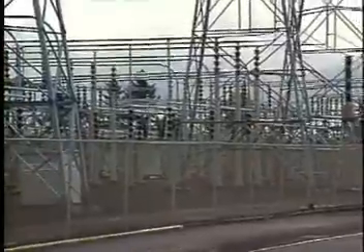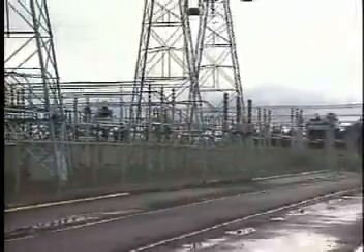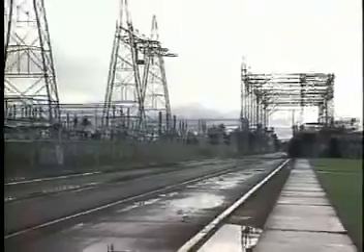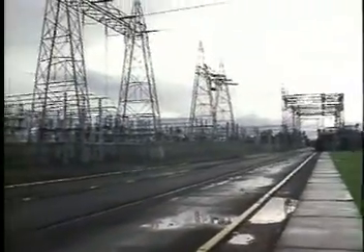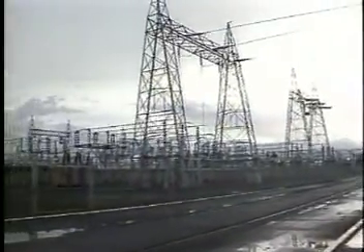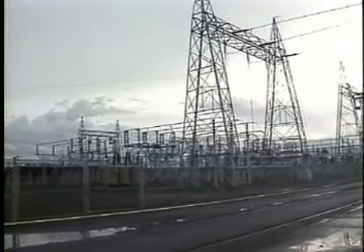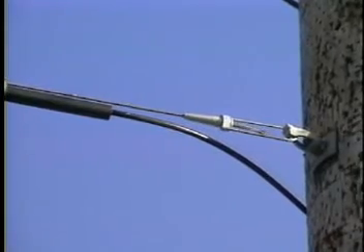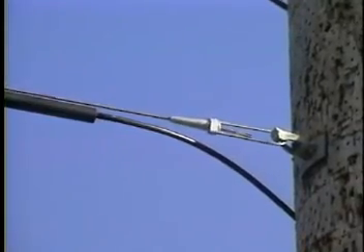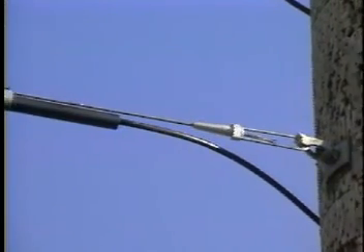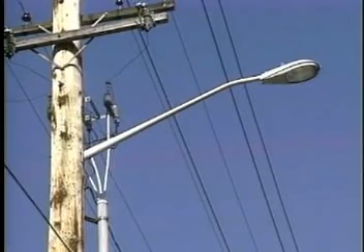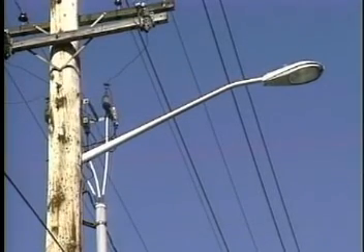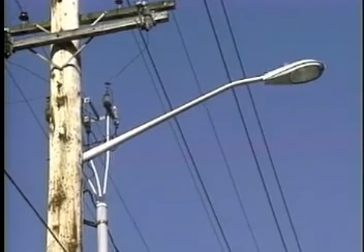In applications where high voltages are nearby, it is best to use an all-dielectric self-supporting cable to eliminate damage and safety hazards caused by induction. However, where this is not possible, metal messengers must be grounded periodically along the route, usually at 3 points per kilometer.